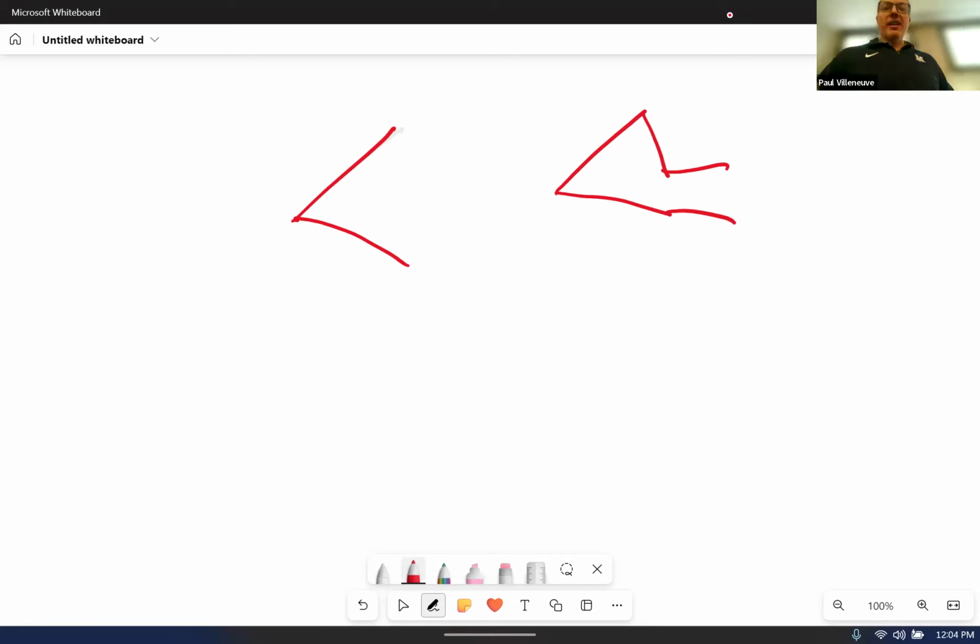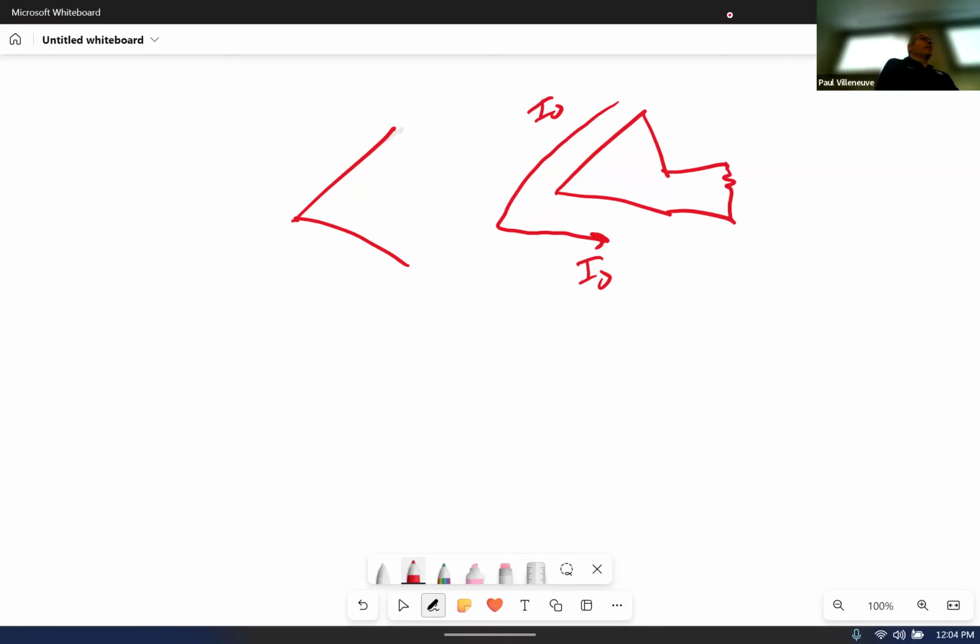And the reason being, which will make a lot more sense to you in later classes, you have a current in here called the zero sequence current, that if you break the delta, you can actually measure I0 here once you break the delta. So that used to be very common back in the day too, when you were trying to look at ground fault currents.